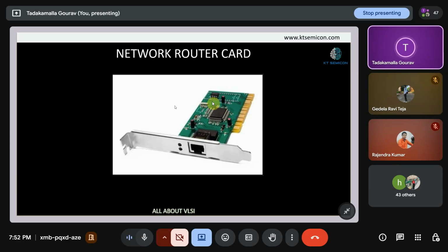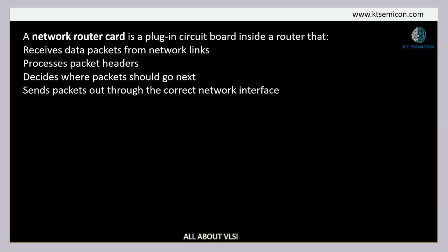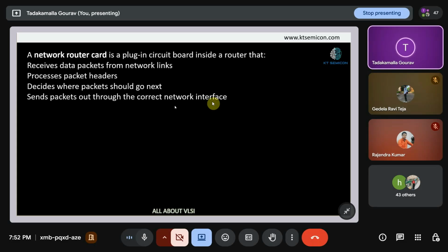And if you want to implement this particular chip, you can directly implement it on an ASIC. But instead of that, many companies develop their prototype on an FPGA chip and test it. After that, if it is working correctly, they go to mass production in terms of your ASIC, right? So this is where you can expect an FPGA or a PLD to be used.